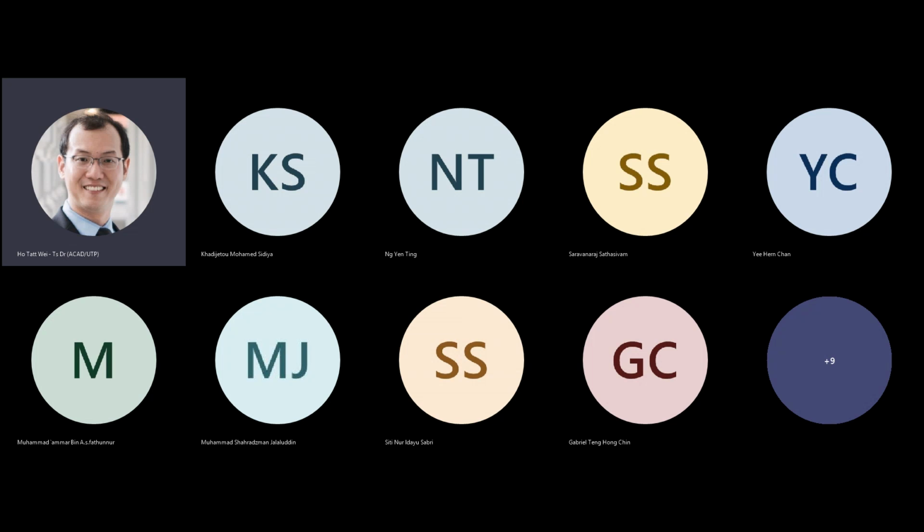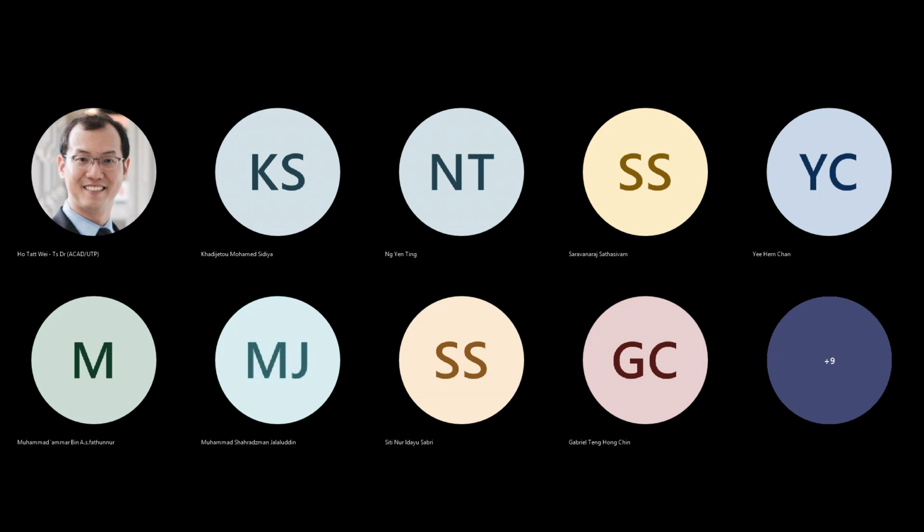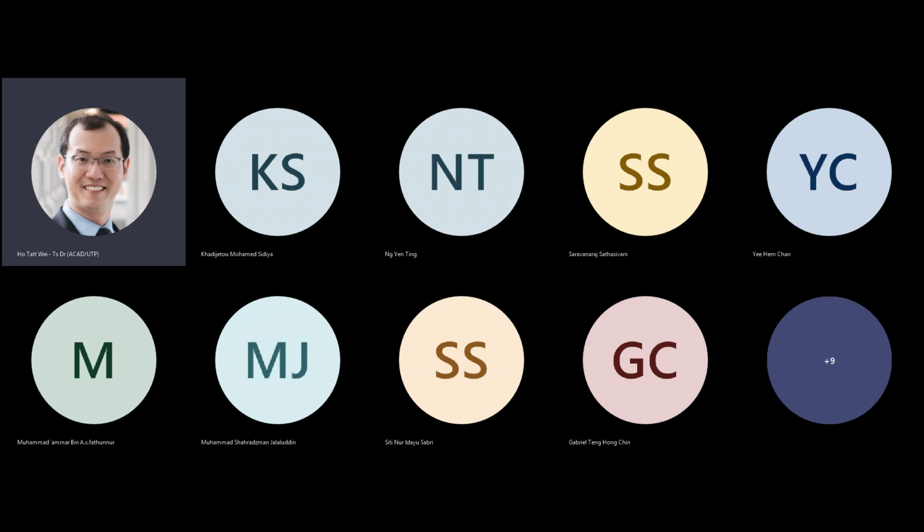Well, referring to you have your, let's say again, my PMOS, my NMOS, N well, N well, P well. So we've already gone through that there is a capacitance here, okay, capacitance from this point to ground. So that would mean that there's a capacitance sitting here to ground, right? And that's this part here. But if you look at this, what is N? N is basically a region where there are a lot of free electrons. What else has free electrons?